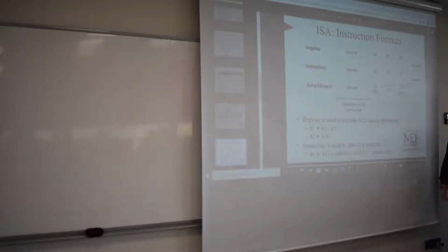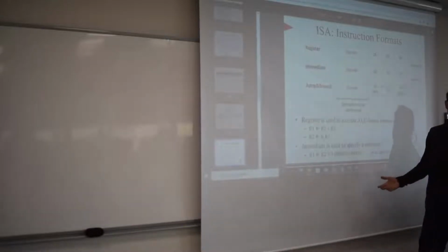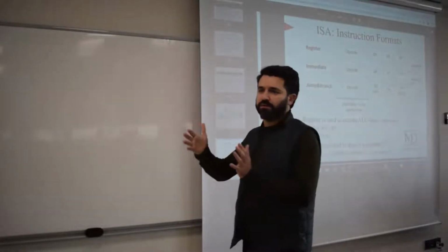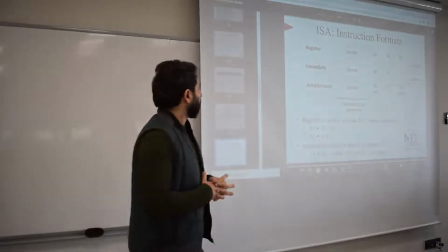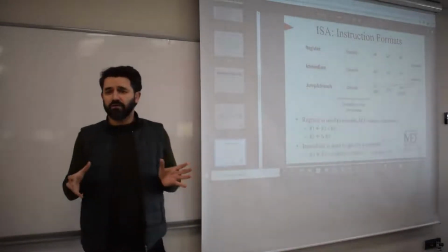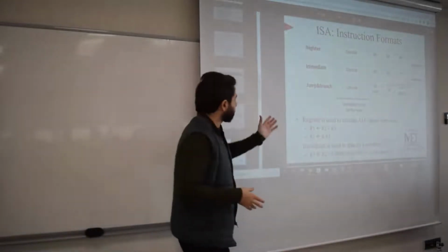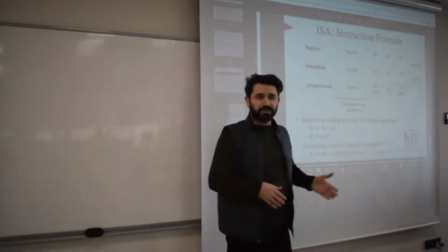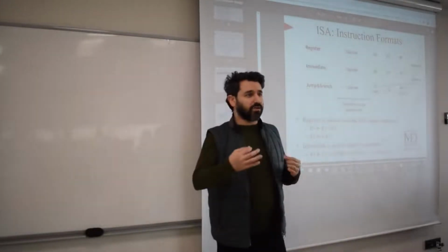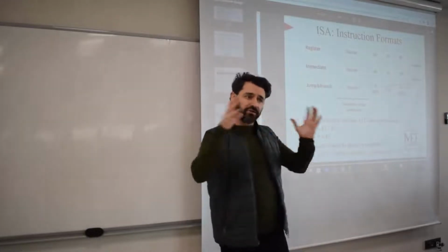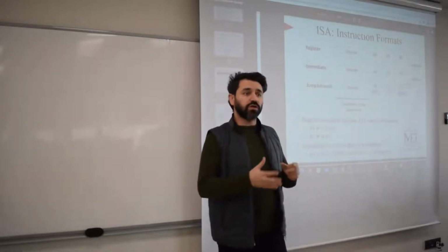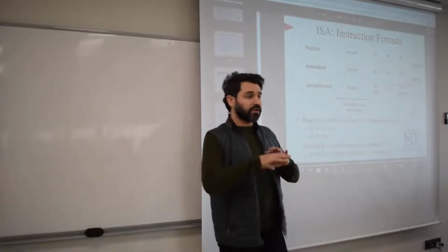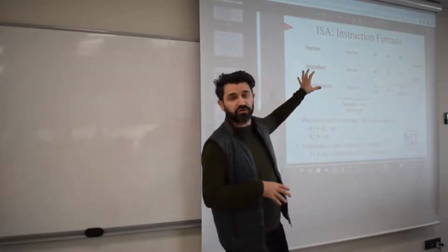As you all know, you don't want your hardware to do a specific job. You want a set of functions to be implemented with the hardware. The way that we classify those sets of instructions is this. This is called instruction format. When I say register type, it's not a specific instruction like add or subtract. I'm talking about a class of those instructions. So including addition, subtraction, XOR operation, these are all the same type, register type.